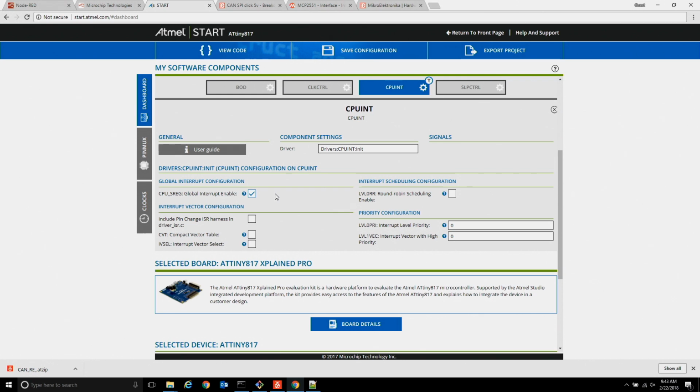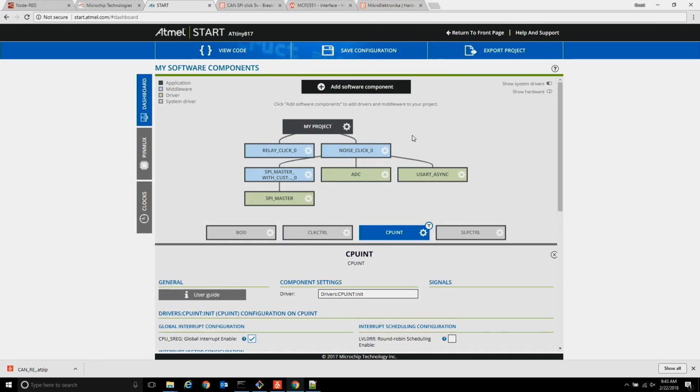Okay. And all of those modules at the bottom of the upper part of the dashboard, those are all core centric modules, right? Yes. So when you create just a plain project, these modules will be there. These are the system modules. Always there. So it's a must-have. And those are going to be things like if you're going to enable sleep modes, if you're going to do brownout detect. Yes. Okay.